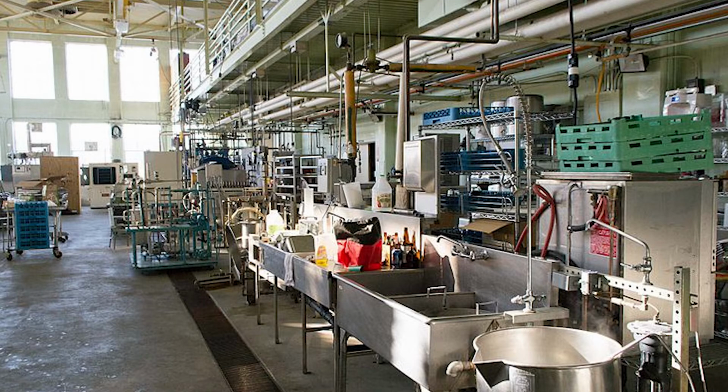To correct these levels and bring them to an acceptable range, consider sweeping dry material to be disposed of before washing floors or equipment. Pre-treating water within a facility with a system, such as dissolved air flotation, to separately collect suspended solids and fats, oil, and grease before entering the sewer may be cost-effective in situations where facilities have already optimized processes and still incur high surcharges.